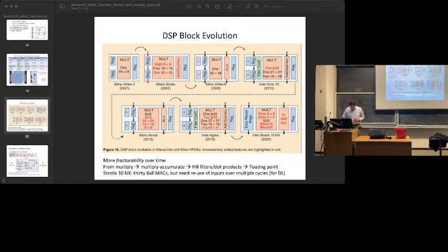And then this last one, as I said, is a little different. And this DSP block actually is targeted at deep learning. It wouldn't be very good for wireless signal processing because it actually can't do 18-bit fixed point. It can do 32-bit floating point, but it can't do that many 18-bit fixed point, et cetera. So it's really targeted at deep learning. And let's talk about that one a little bit.